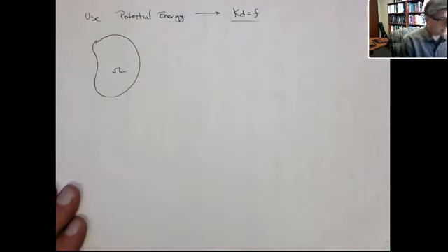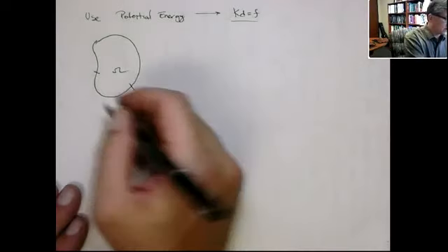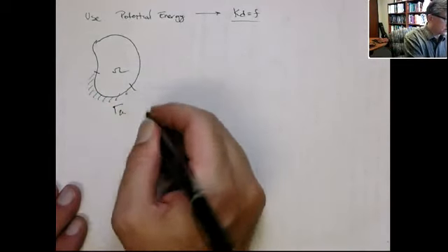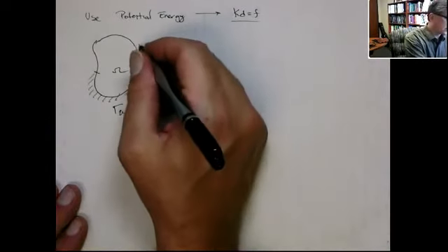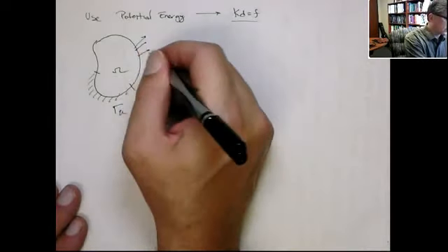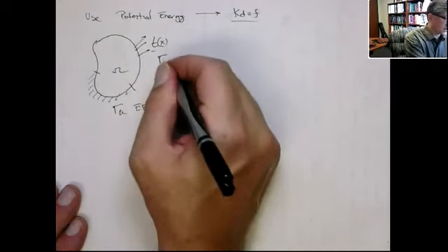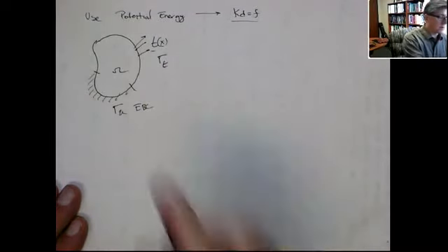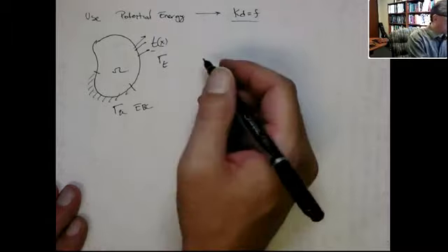So we have this computational domain, omega, right? Its boundary is broken up into two parts. One part where we have essential boundary conditions prescribed with the displacement, and then another region where traction is prescribed, the traction vector is prescribed, and I'm going to call that gamma t for traction, gamma u and gamma t. All right? And every point has to belong to one of those two domains, and there can be no overlap. All right.